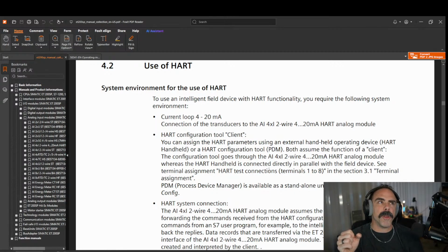Normally, you're going to use 1 extra variable. Maybe there's a temperature or a quality code, like a reliability factor, a totalizer function, something like that. You really just want 1 HART variable. So Siemens said, we're going to give you a configurable 4 variables across all channels.